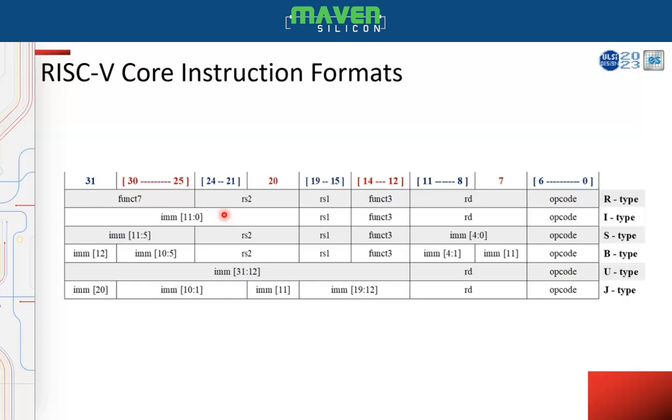At the end of the day, our driver has to drive a 32-bit instruction. But we cannot generate the complete 32-bit instruction in a single shot, because the 32-bit value cannot be completely randomized. Depending upon the type of instruction, we have to decide what should be the opcode value, the funct7 value, or the funct3 value. The RISC-V ISA defines the opcode, funct3 and funct7 values for various instructions.